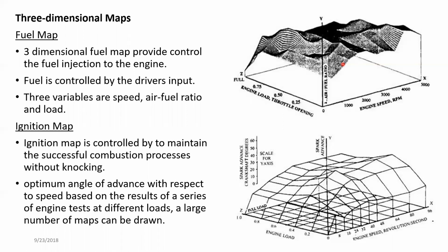While this is happening, the ignition system listens to the knocking. If knocking occurs because of the fuel reduction based on the feedback from the lambda sensor, the ignition system understands that knocking has started and we have to take action. So retard 1.5 degrees.